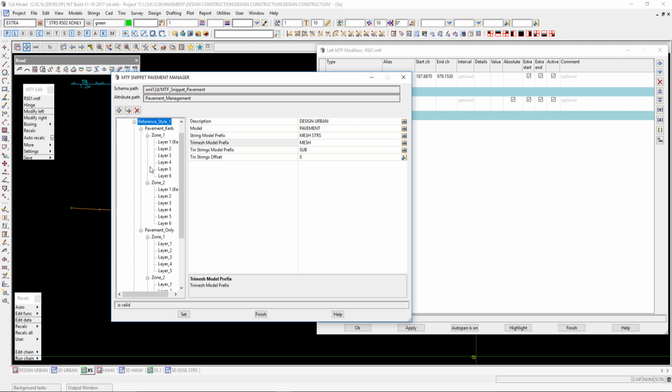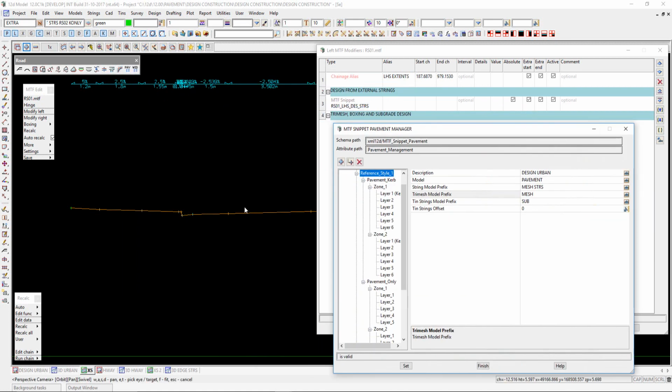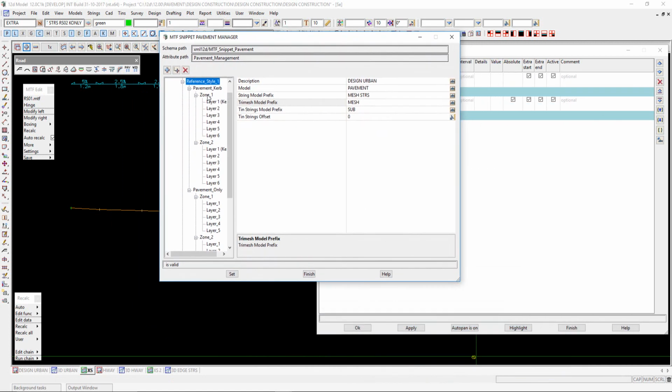So again, inside the zones here, I have one for curbs. In that case, I do have a curb profile, and I'll set up a curb layer. This is one that is a curbing channel. This one here is just a bus drain. So again, under here for a curb one, you've got the curb profile, different layers that support that particular design profile. This is in previous videos. You can have a look at how to add and create different styles and layers and zones.